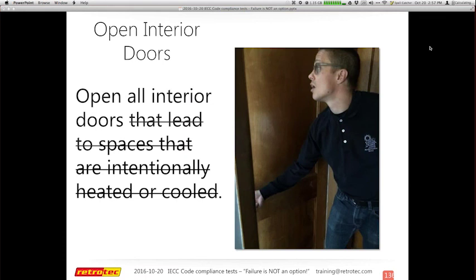I think you're going to find sometimes the huge leakage is from a closet that had a gap above your head that you forgot to see, or especially built-in components like for stereos or audiovisual. Those are some of the worst, because these guys come in after the fact. They put huge holes in the back of the wall going up to the attic, and you really want to make sure that those kind of doors are open because you can feel the air flying through them when they're open and you're doing your test. So again, those are huge things that actually will make your path a whole lot faster.